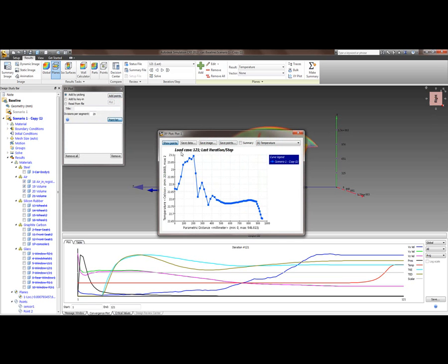You can see where I was a little bit irregular there. I started at the top and I went back and did a few. You can see where it's followed that chart. But you can see, from the vent, it's slowly getting cooler. When I'm up to, say, the average person's head height, it's now a comfortable position and you're in a comfortable zone. So the temperature's being distributed and cooled effectively as we would want it to.